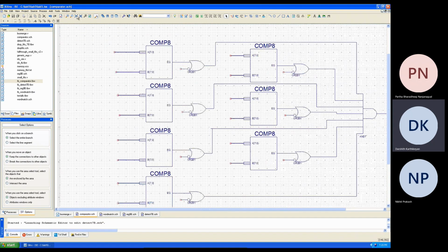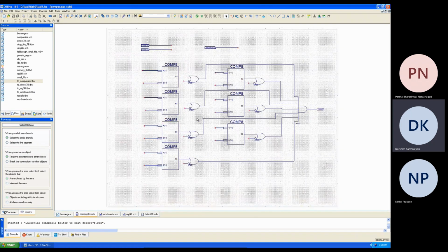This is the schematic for the comparator. Here, basically, we are taking the 56-bit pattern and comparing it against the 56-bit data. We have a feature called a mask, where we can mask the corresponding byte to be compared or not. Even if the pattern is recognized and the a mask bit is turned off, the comparison result will always be a 0.